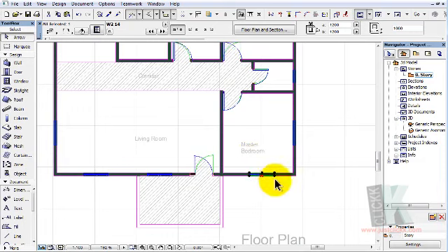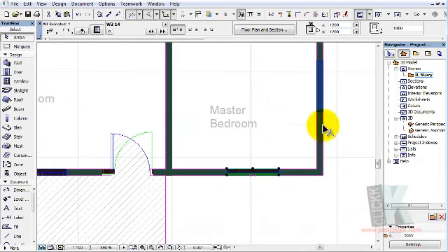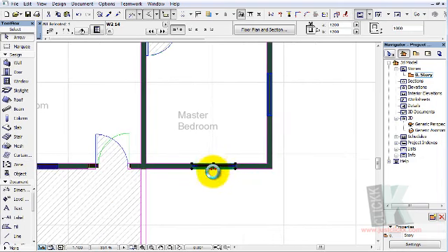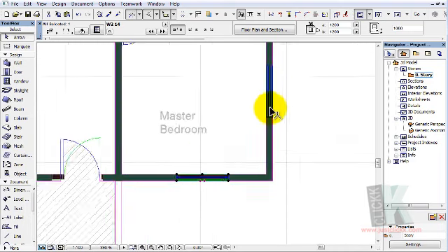Okay, you can't drag this to this place because this is not on the same axis. You can only duplicate objects like this because these objects are dynamic update, as in they're embedded to the wall, so you can't drag them out of the wall. And dragging it to the horizontal, the vertical aspect of the wall, it's simply not possible. So what you do is you have to recreate the horizontal type.